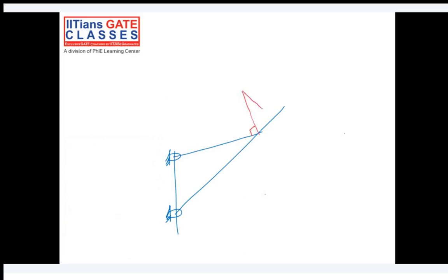And this is the velocity of slider. Here we have the slider. This is link 2. This is the first link, second link, third link is the slider, and fourth link is this. So V3 is the velocity of slider. This is L2 omega 2, L4 omega 4. Clear?